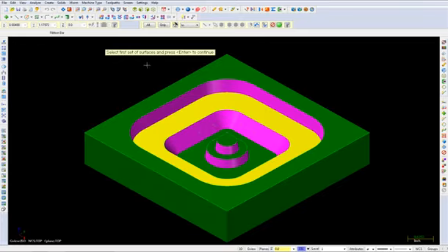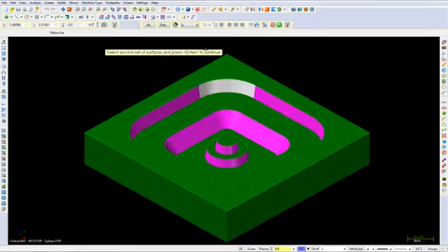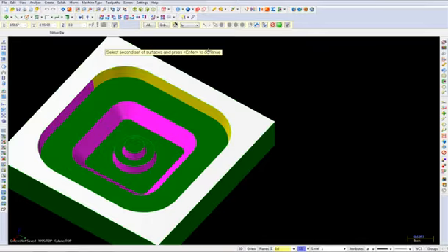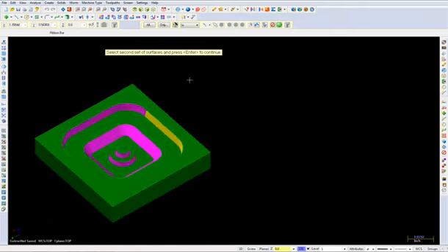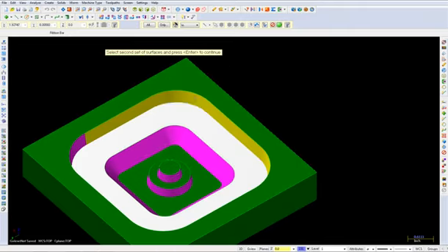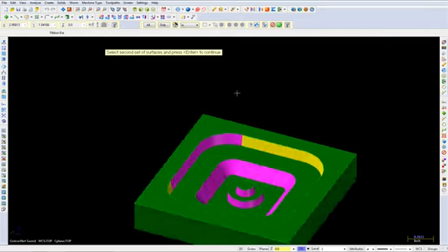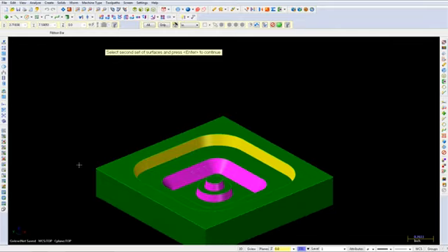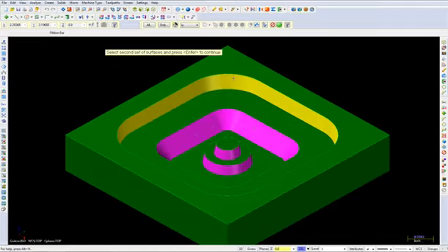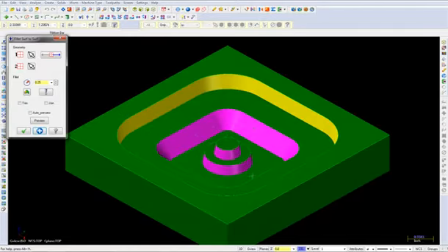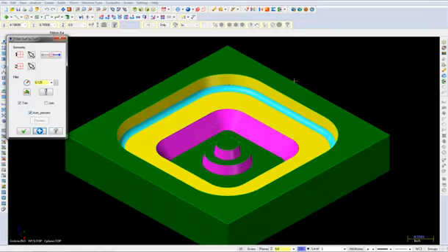Select this surface here. Press Enter. Then select all of these surfaces as your second set of surfaces. And choose the End Selection button. Change your fillet radius to 0.125. Enable Trim and turn on the automatic preview. The fillet should appear as shown. Select the Apply button.